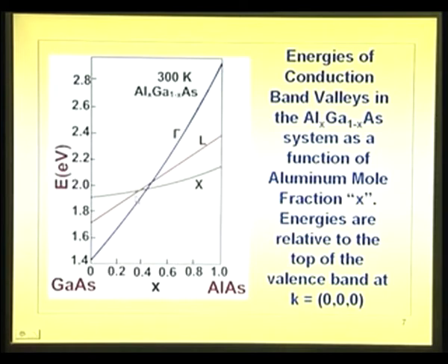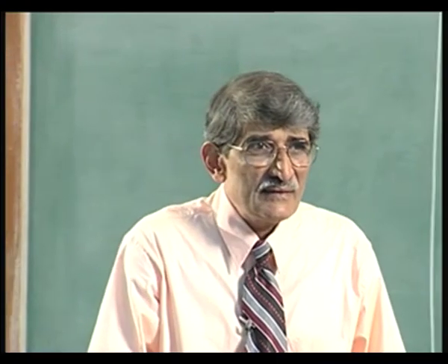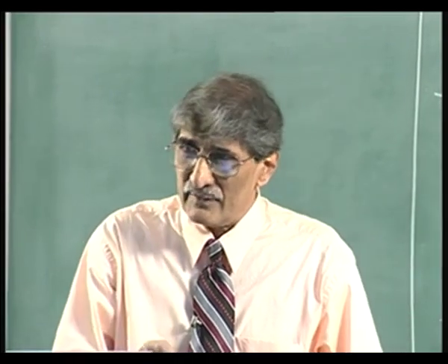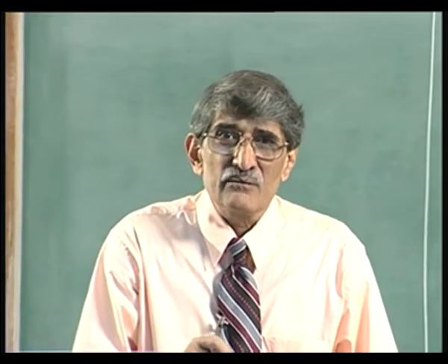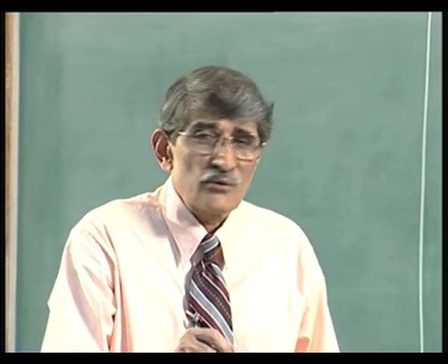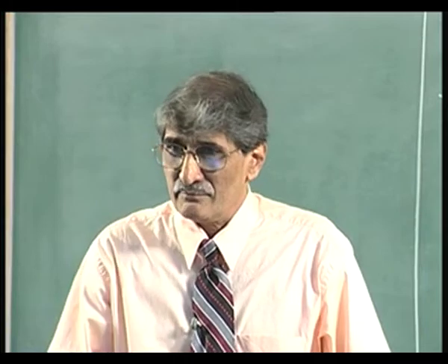So, from this diagram, if you just draw straight lines, you will not get that 1.93. In fact, when I drew the straight line earlier, I put 0.3 corresponding to that, but it is a very crude approximation. The real thing is that. If you see the indium gallium arsenide, as x is varied, it will not be really straight. So, the band gaps that you really get are slightly different. Where x equal to 0.47 gallium concentration, you get 0.75 electron volts band gap because of its nonlinearity.